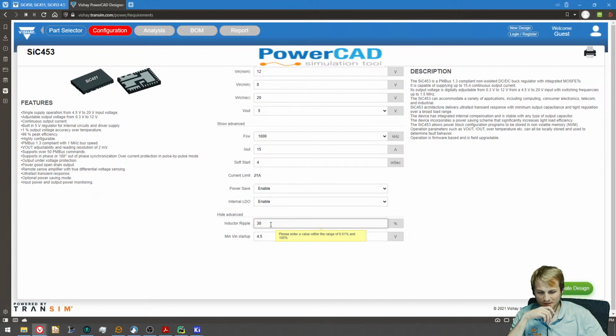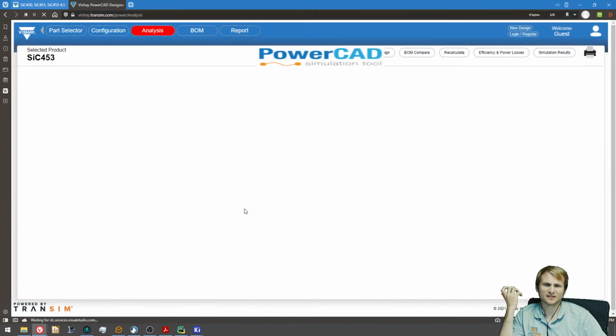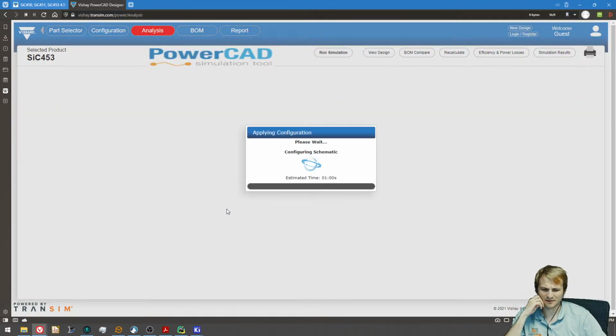But it's really funny because even with a value that high, they still were going with a 1 microhenry inductor. So if we change it to 10, it'll change, but it still doesn't change the obnoxious amount of output ceramics, which is really weird.